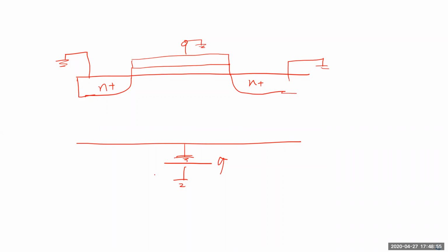At all the PN junctions, the depletion width is going to be more compared to the previous one, because previously it was 0 at N, 0 at P. Now it's going to be reverse bias, because it is a negative potential. The confusion comes from here. With a negative potential, at this particular position, what is going to happen?